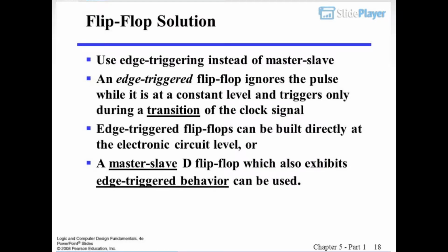Flip-flop solutions use edge triggering instead of master-slave. An edge-triggered flip-flop ignores the pulse while it is at a constant level and triggers only during a transition of the clock signal. Edge-triggered flip-flops can be built directly at the electronic circuit level, or a master-slave D flip-flop, which also exhibits edge-triggered behavior, can be used.